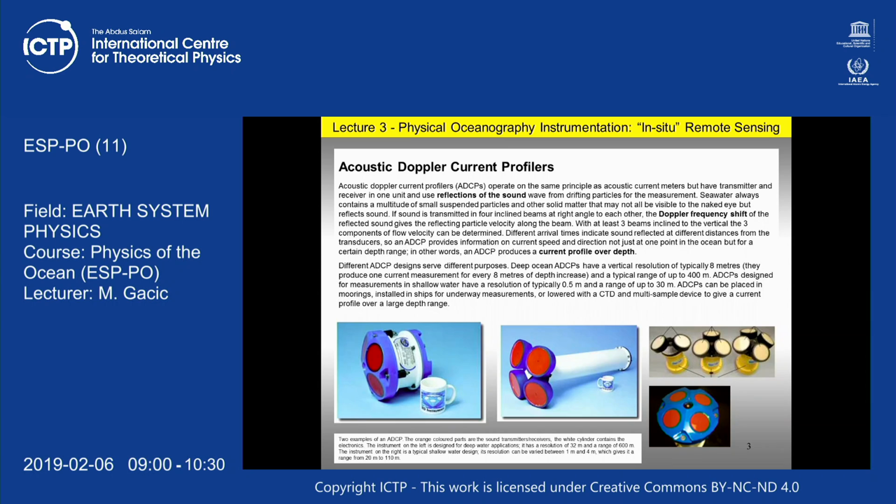But not only that, you can estimate the outflow rate of this dense water, what I told you before, which then determines the changes of the flow in the Ionian Sea. And if you decide, okay, my water which outflows has the density of 29.2, so you limit your area where this dense water outflows, and say, okay, this is my water which outflows and which is the dense water formed in the Adriatic.